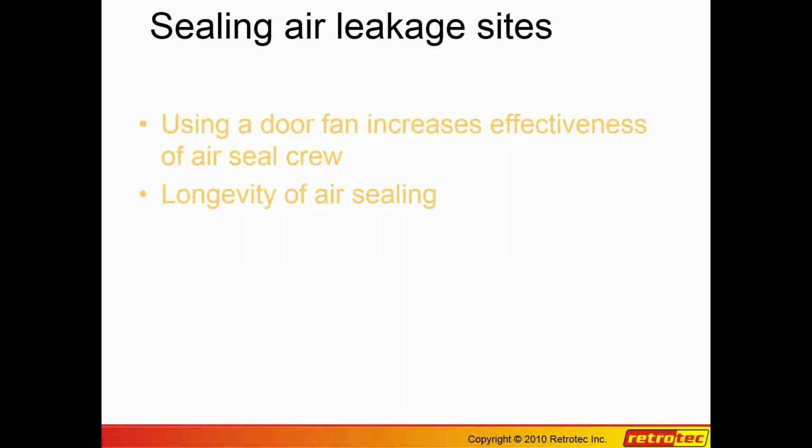So your blower door, or whatever you happen to be using to measure the air leakage of your enclosure, has a really important function: to teach you how different components are leaking and the effectiveness of your air sealing measures.